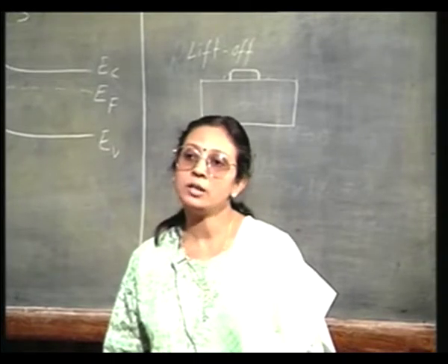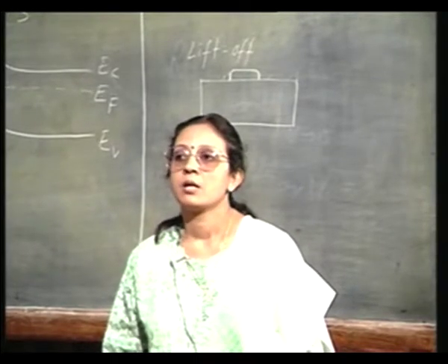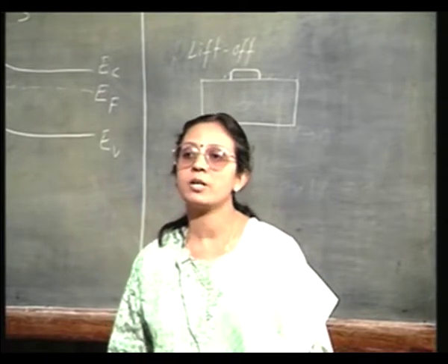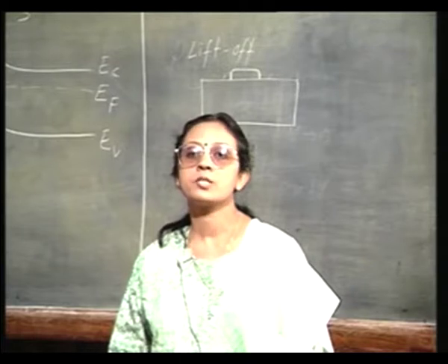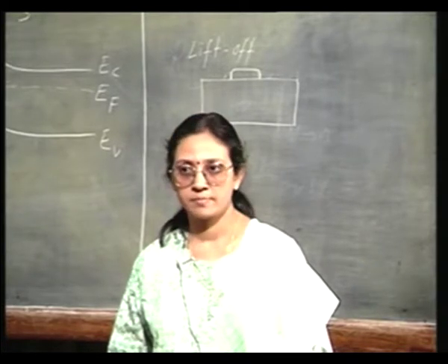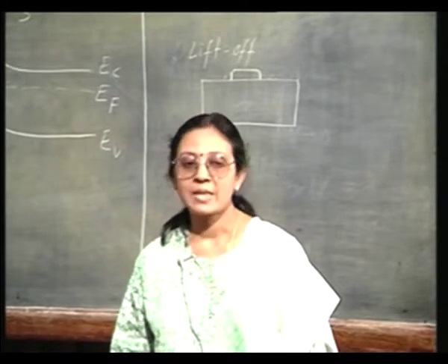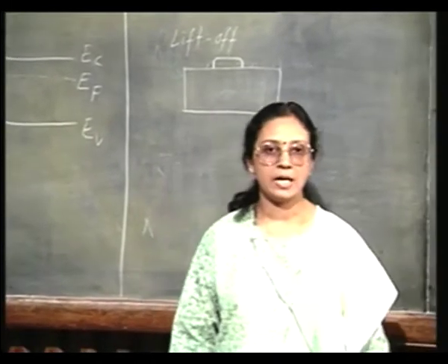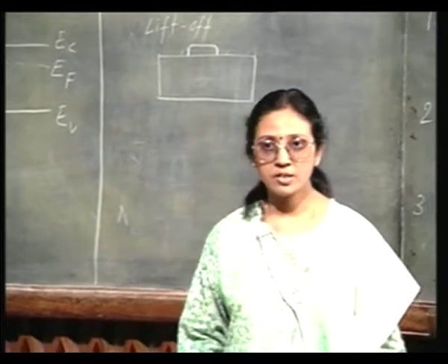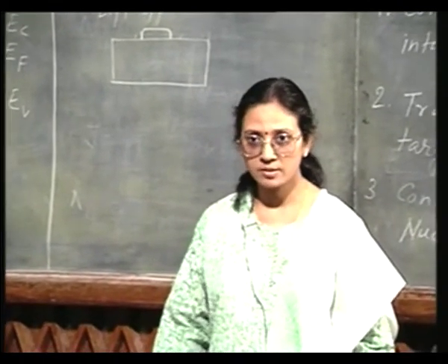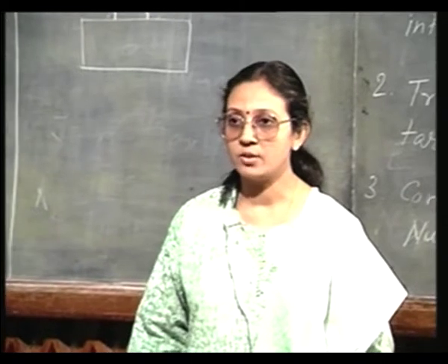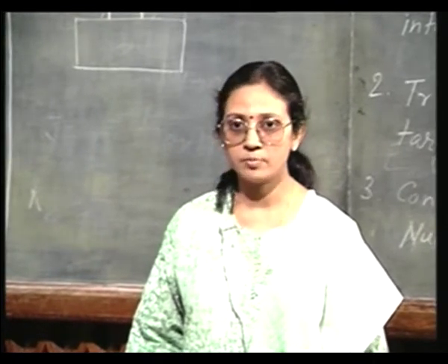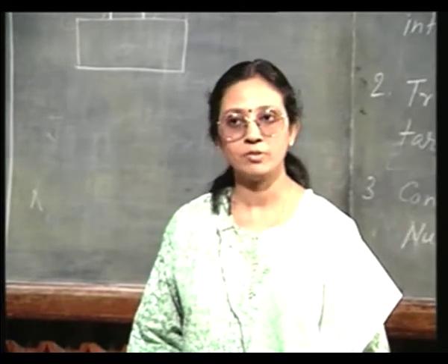So, you see all these requirements. Because of all these requirements, it is important for us to know the deposited metal layer thickness. And the metal layer thickness can be measured either in situ, that is while the deposition is taking place, or ex situ, that is after the deposition I take out the substrate, take out the sample and try to measure the thickness of the metal.